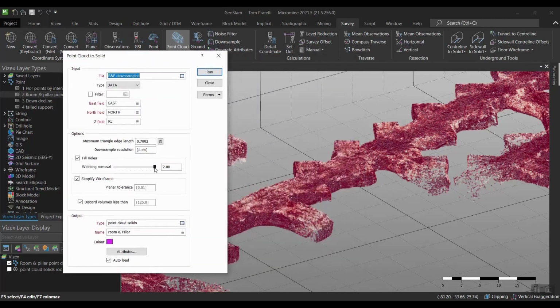Webbing allows us to effectively control areas in a point cloud where there are voids, and how we deal with voids or any lack of information, for example, that we might have incurred from shadows or some areas that just didn't scan well. So with the webbing tool, we can control that. We can choose to web over it, or if we're not interested in doing that, we can slide down and make sure those areas that we might not want to web over or cover over aren't covered.